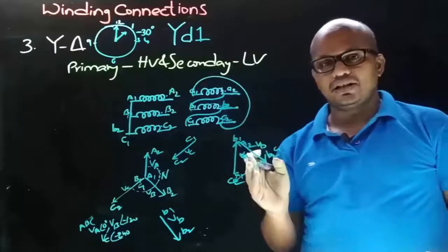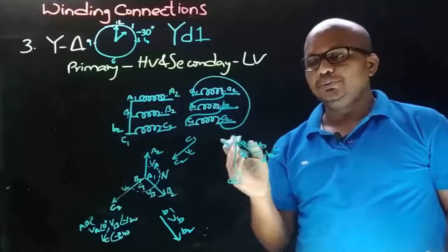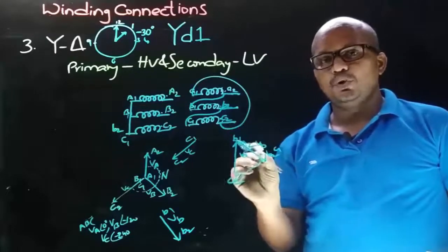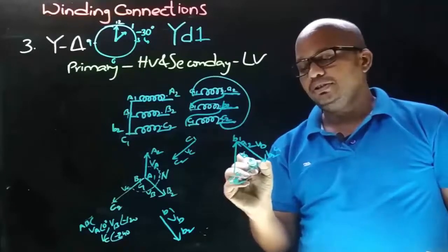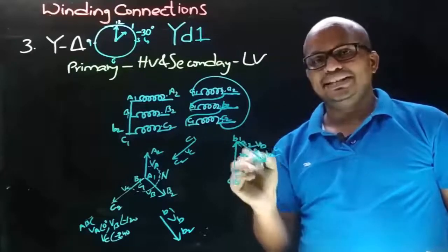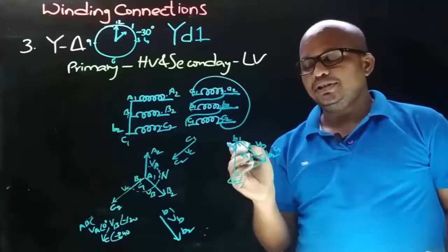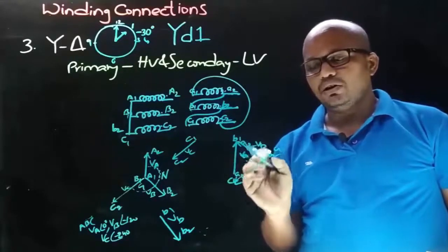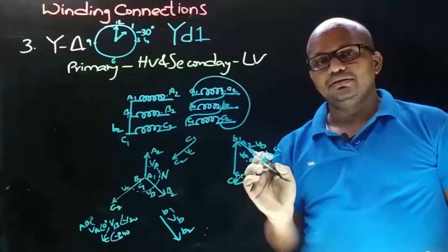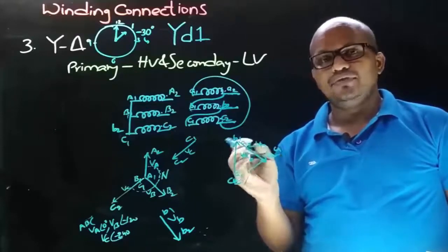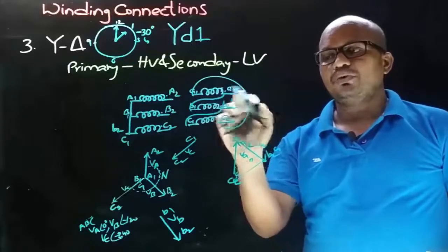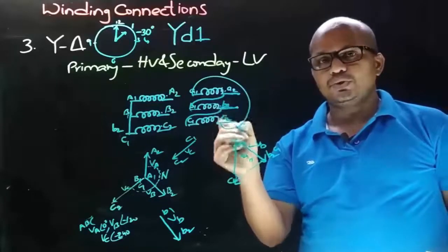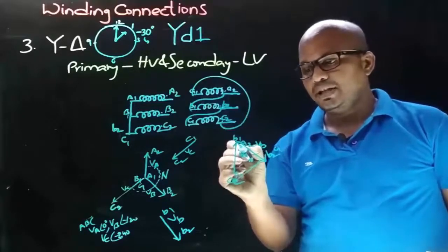And as this is delta connection on secondary side, we need to draw the phase to neutral voltage for comparison purpose. So let this be the imaginary neutral in delta connection. And now we need to decide if A2N or A1N is the phasor for comparison. And observe that in VA, the connection is taken from A2. So the phase to neutral voltage for comparison purpose is A2N.